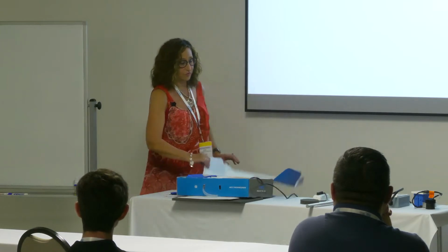All right. I do have one more clarification question. You said that they prefer vacancy over occupancy, and why? They prefer vacancy over occupancy because vacancy requires initiation. So with a vacancy sensor, you have to physically turn it on. We're going to talk about control intents in just a second. In my control intent narrative, it says a positive reaction is required to initiate the luminaire or something to that effect, over an occupancy.